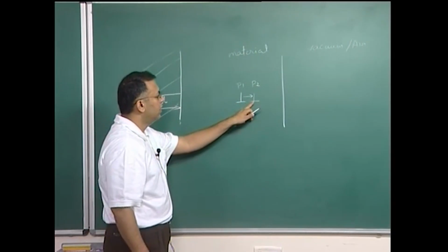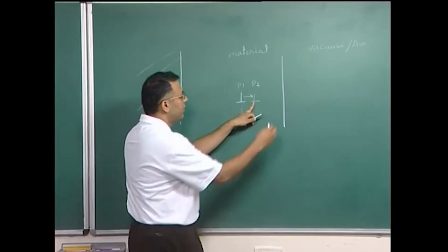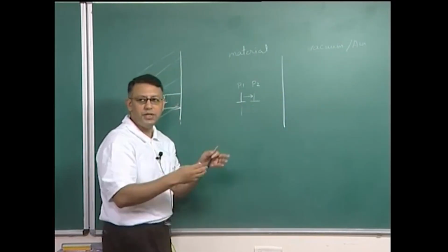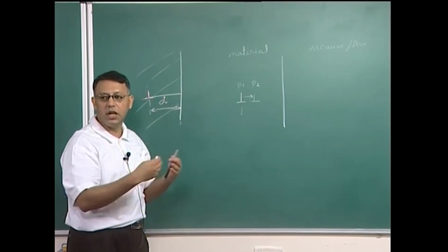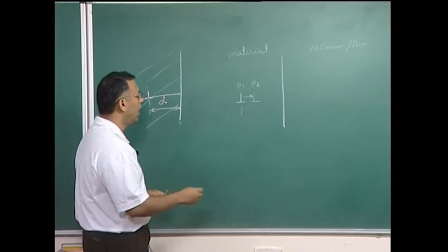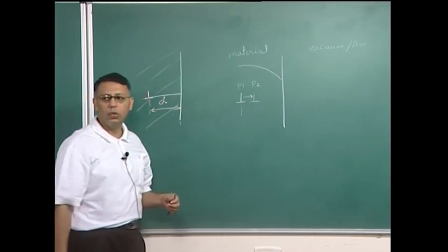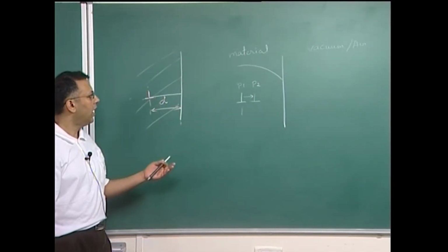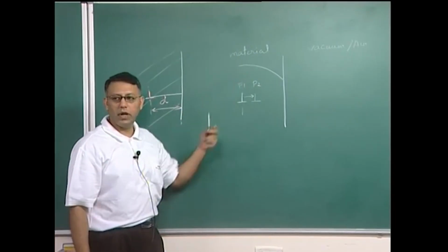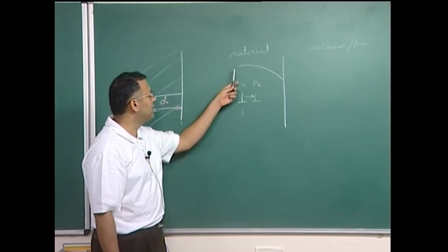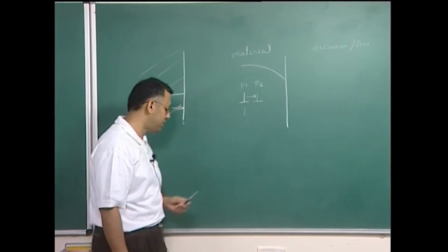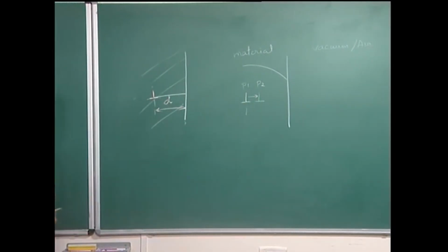Here the dislocation is closer to the free surface, which implies that more of the intense regions of the dislocation have been relieved. That means the energy of the dislocation is going to be lower, and therefore continuously the energy of the dislocation will be lowered as I go towards the free surface. And since the gradient of an energy is actually the force, that means the dislocation will feel a force towards this free surface, which is called the image force.